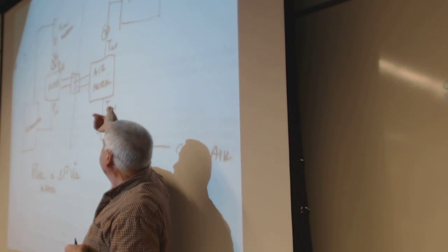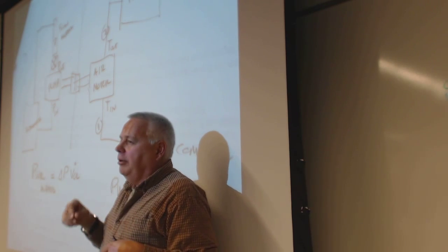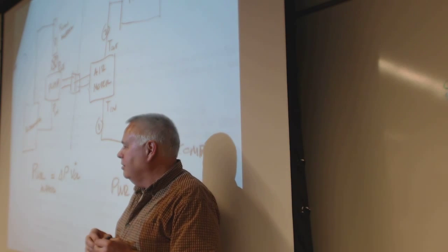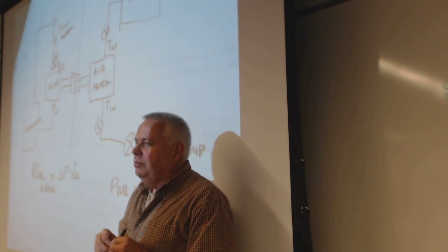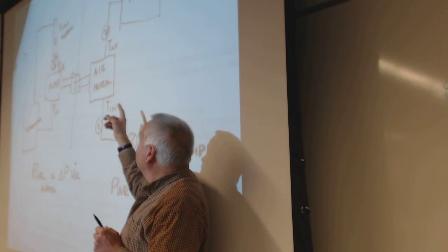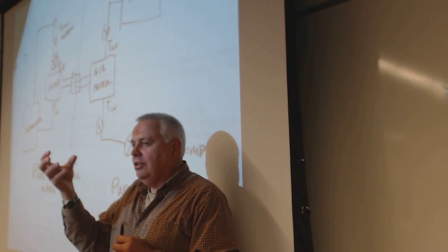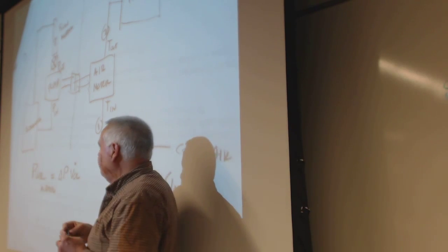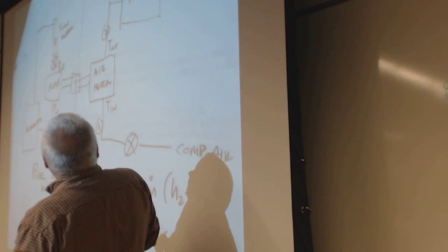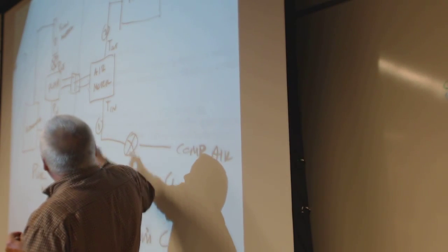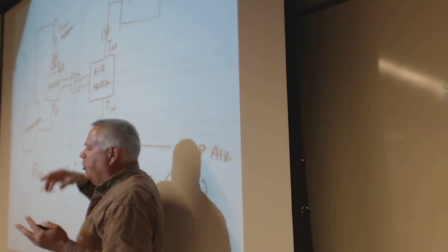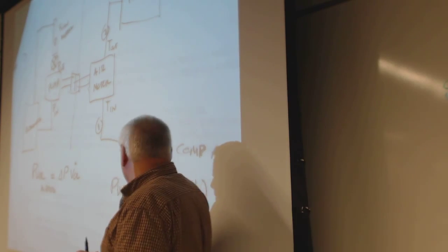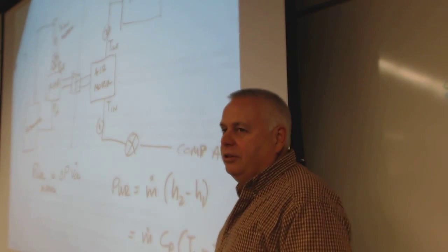Well, air motors, actually, the outside can come off cold, like refrigerated. It'll frost. Some of you, not all groups, but the groups with higher RPMs, will probably come out frosting the outlets. Temperature drops. So, it turns out that the temperatures kind of report that whole pressure thing. It is about pressure times volume. We don't know what the volume of the pump is, but we can do this C sub P times temperature, and we don't need to measure the pressure.